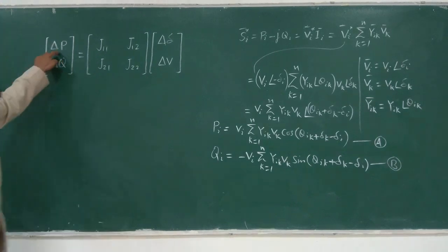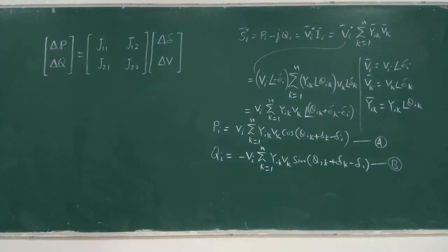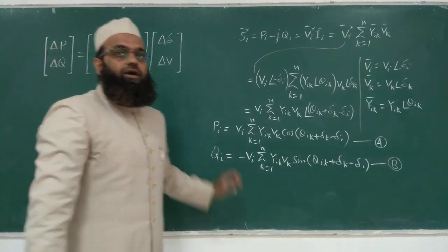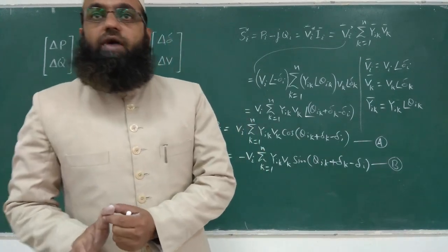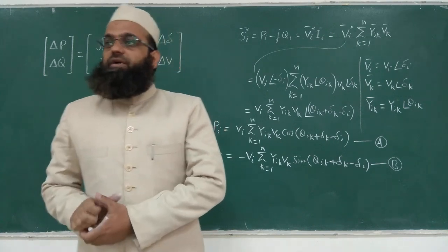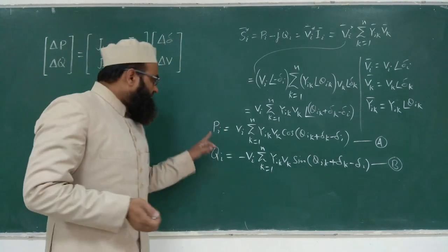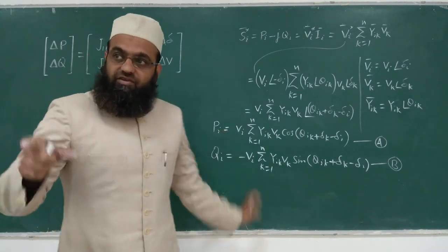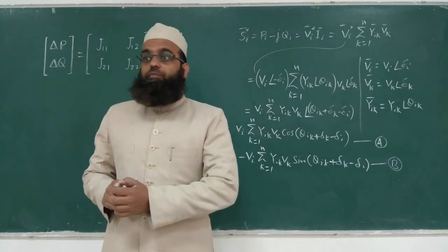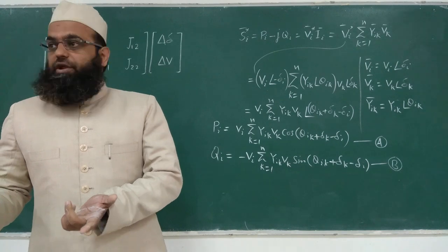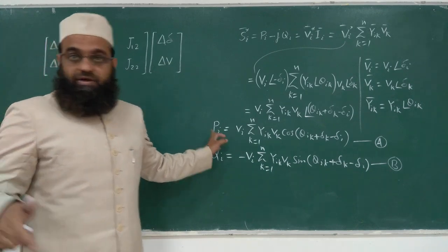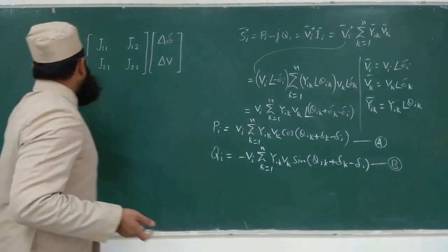So what is this delta P? Delta P is nothing but the difference of a specified value and this variable, right? Yes. Variables are Pi, Qi, Vi and delta i. For any bus, each bus of the power system is characterized with four variables. So this is not a fixed variable. So ideally it must be equal to the specified value, either PQ or PV. Both buses are having P as specified, is it not, whether PQ or PV. So this should ideally be equal to the specified value. But nothing is ideal. That's why we have introduced this variable del P.